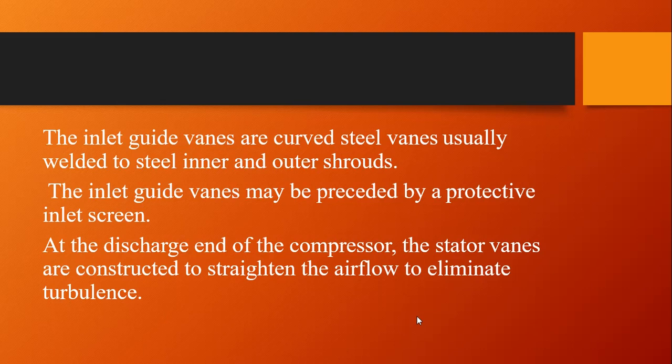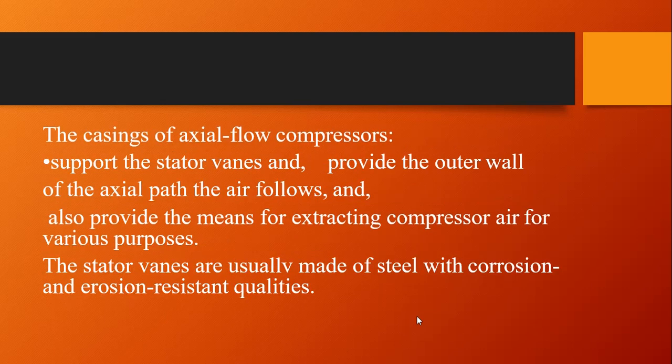The stator vanes are constructed to straighten the airflow to eliminate turbulence. Inside, they were directing it to the next stage, but here at the discharge they straighten the flow.